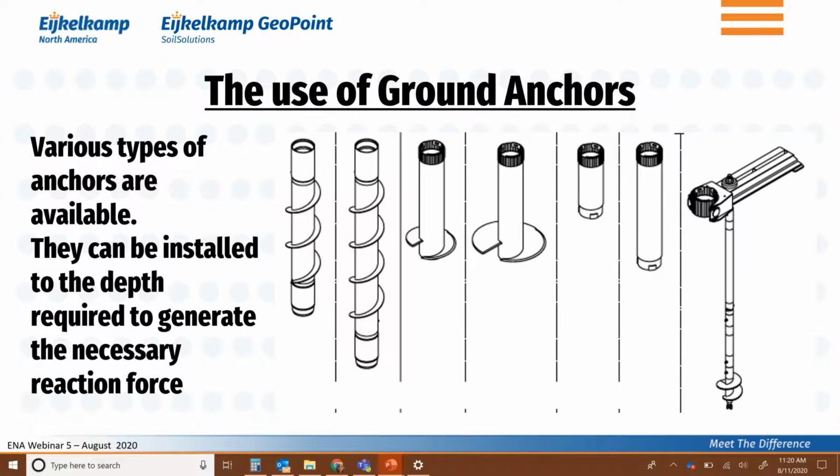And what you see here are different types of ground anchors. You see the single piece pipe with the helix, whether it's a smaller or larger diameter; we can provide different diameters. You can put the extension piece in there to put the thing deeper. You can also put pipes in there with a continuous flight. And then finally, you can also put a balance beam in there, where you now suddenly have this thing sitting to the side of where you do your CPT.